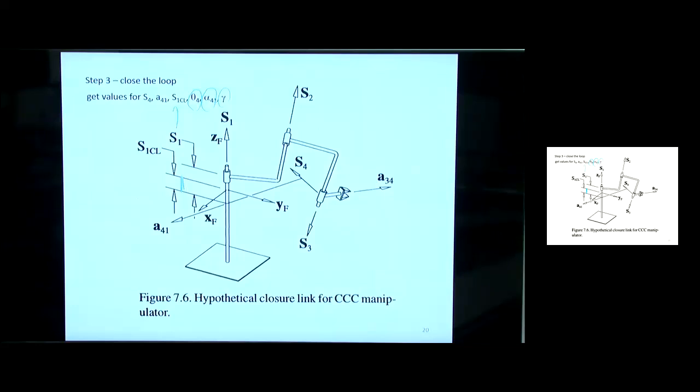So how does this close the loop thing come into play? Because when we do the spherical, the spatial 4-bar that we're going to get out of this, we are going to solve for S1. The robot wants L1, but I know that. Oh, so the robot wants L1. Oops. So it turns out that the L1 that it's going to get is the S1 that we calculate minus S1 closed loop that came out of here.